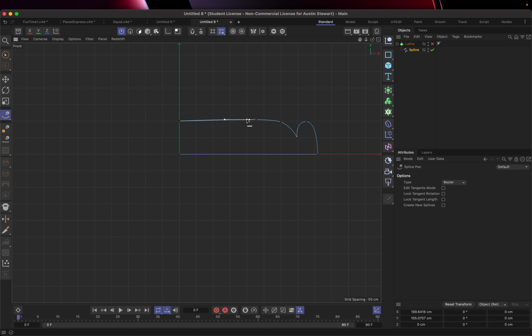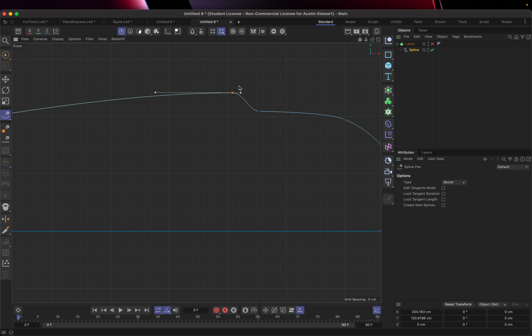And then I'm going to have a point here where I want to lift this up just a little bit to make this happen. And you'll see that this curve, what I'd really like is for this curve to not curve the way that it's currently curving. So I can probably click this, but you'll see that's actually warping everything, which is not what I want to have happen. So in this case, I am going to select this point. I'm going to right click on it and say hard tangents. And what that's going to allow me to do is select this following point here, and I can just click on this one handle and get a nice curve into a hard point there.